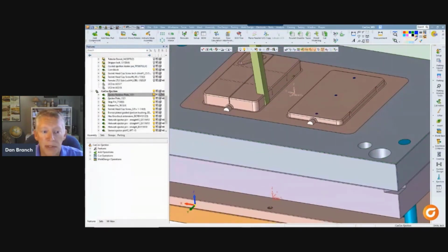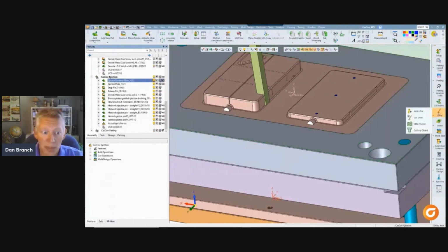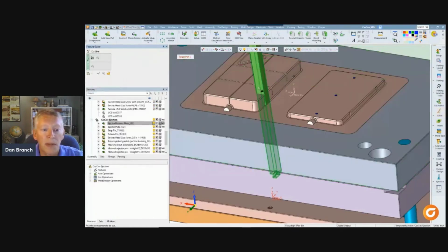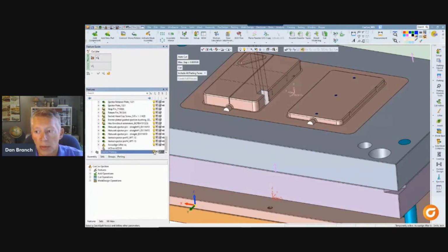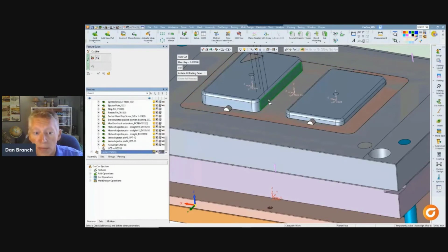So the top of the lifter still needs a part shape on it. That geometry was in the core block, but the lifter pocket took it out. And that's exactly why we have another dedicated function, one made just for lifters. It knows how to get the part shape right from the original quick split part, apply it, and trim the lifter bar off.